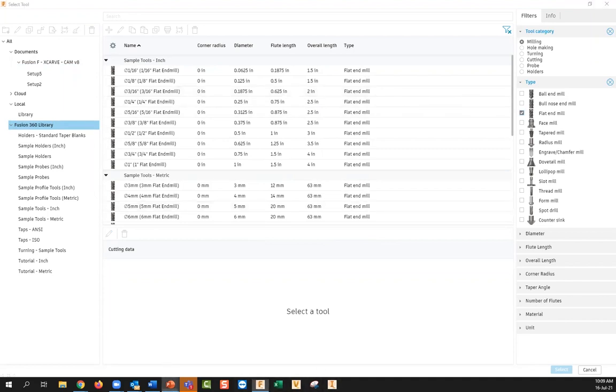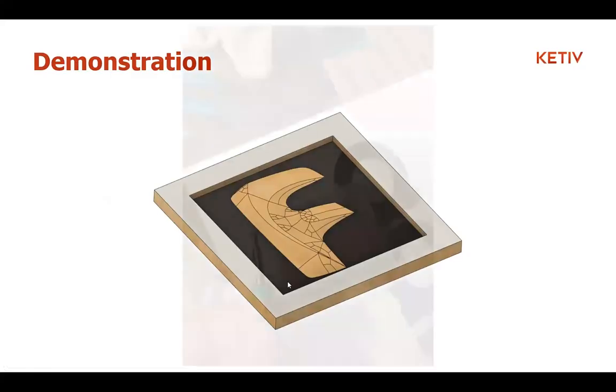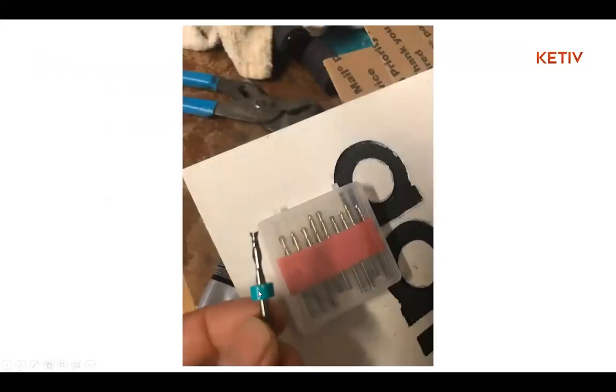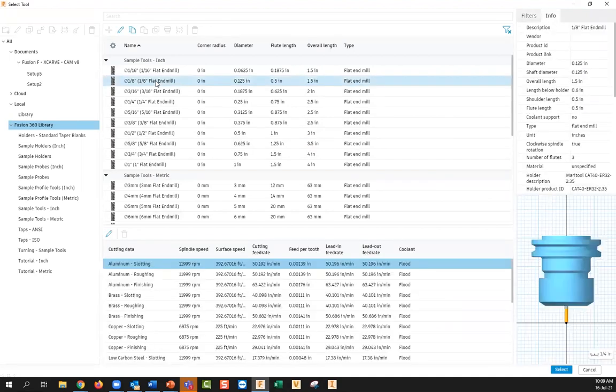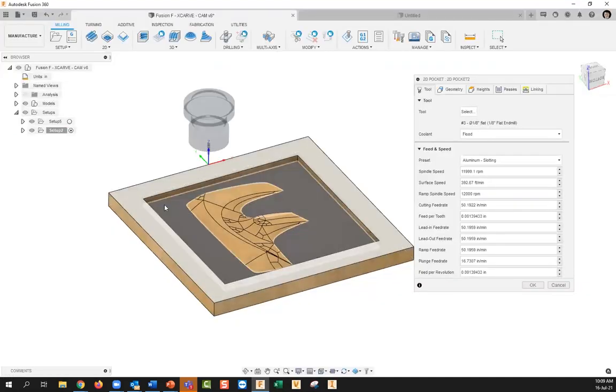Let me show my PowerPoint here real quick. I needed this stopper that came with the machine, this turquoise colored part of the end mill there, whereas the other ones I bought by default don't have that. Long story short, I just needed the stopper. It wasn't tight enough for those other tools. So I ended up having to choose a 1/8 inch end mill. So I'll go ahead and use a 1/8 inch flat end mill, a flat end mill because I need to get this flat surface there.